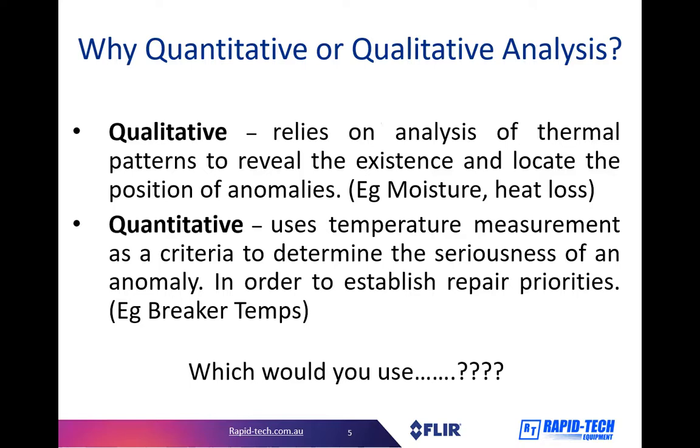What is the difference really between quantitative and qualitative analysis? Qualitative analysis relies on thermal patterns to find your anomaly. All we're doing is just looking at the colors to create a thermal image. Whereas quantitative analysis is actually using temperature readings, which we also receive from a thermal imager.